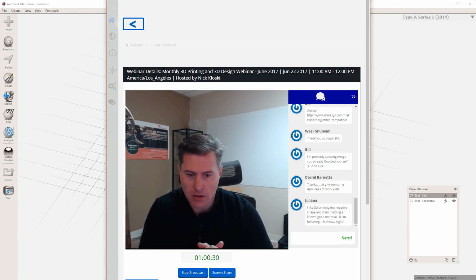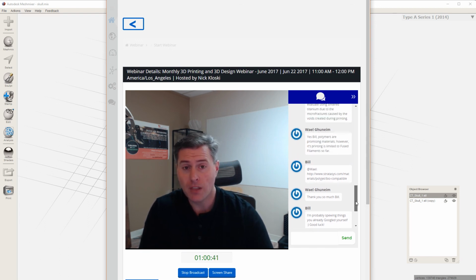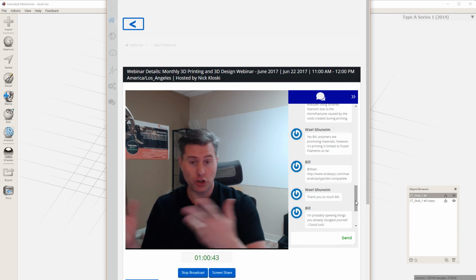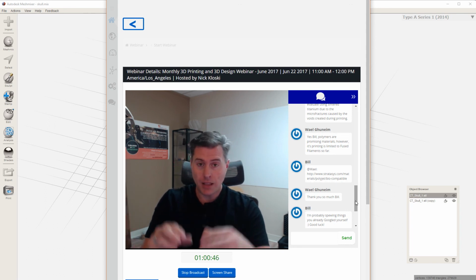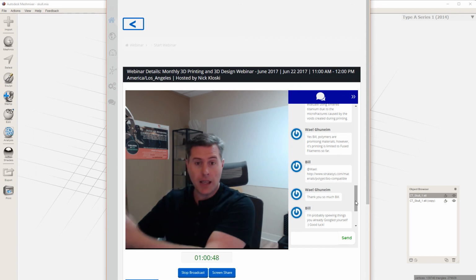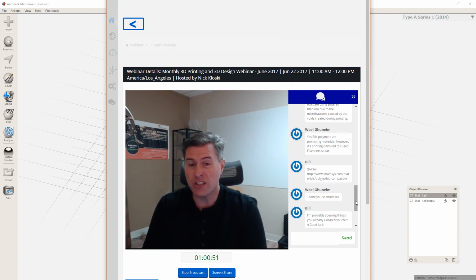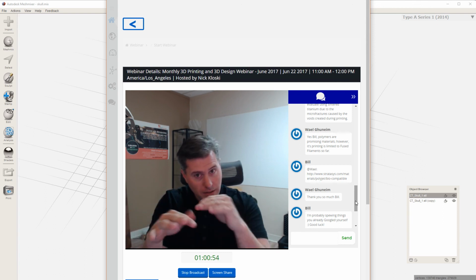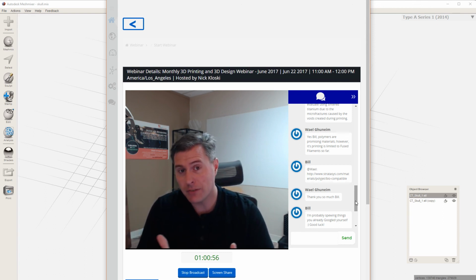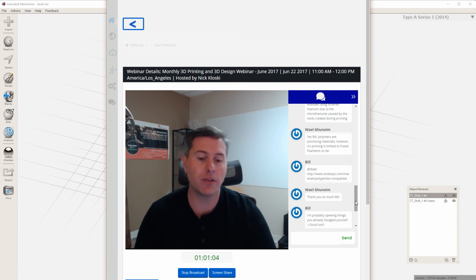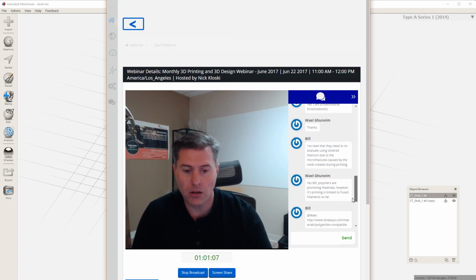Awesome. Glad that helped you, Daryl. And Juliana, I like 3D printing the negative shape and then molding a known good material. Yeah, no, totally. That is totally doable. A lot of people in the traditional manufacturing world model something, and then they model the positive, and then they make a negative out of whatever material. If you get the parting lines right and all of that, you can actually just print the negative. You don't need to print the positive if you're pretty sure of where you're going to cut, and have parting lines for the molds to separate.